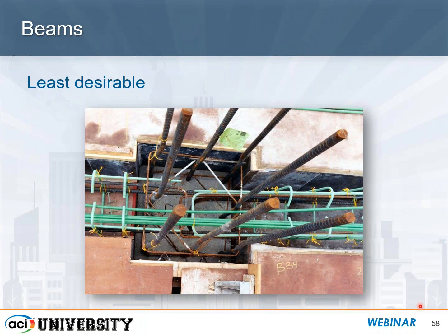All the bars are not in here, and it looks like there's some fairly small bars that are going through the bottom, but again, in general, it's just obvious that you're looking for some congestion issues if that beam is narrower than the column. Again, sometimes we're forced to do it and we have to make the best of it, but that's when all of our other recommendations and guidelines come in terms of using the largest bar size possible to make everything fit well within that joint.